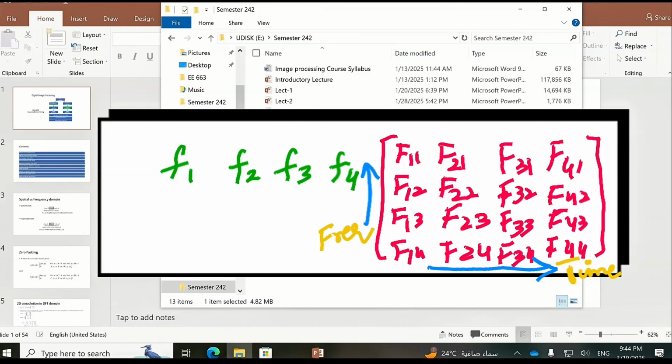Similarly, this is only for the Fourier transform, but if you have, let's say, a Gaussian transform, you can do it too, and Gaussian transforms are sometimes better than the Fourier. So the window size is the hyperparameter. Here we are shifting by 1 unit, but we can shift by 2 or 3 or even 4, and then take another 4. So we have no overlap or partial overlap or whatever, and we call this the hop size, how much hopping we are doing.